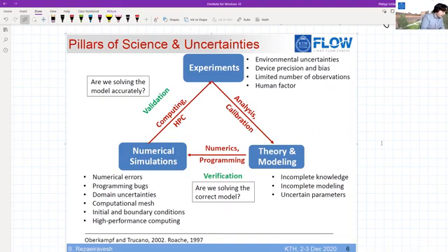In particular, what I like from this slide, which you don't go into in all detail, is that I think the two concepts of verification and validation within CFD are very important. And in short, validation and verification have two different meanings. Verification is essentially related to whether or not I have implemented my simulation method in the correct way.